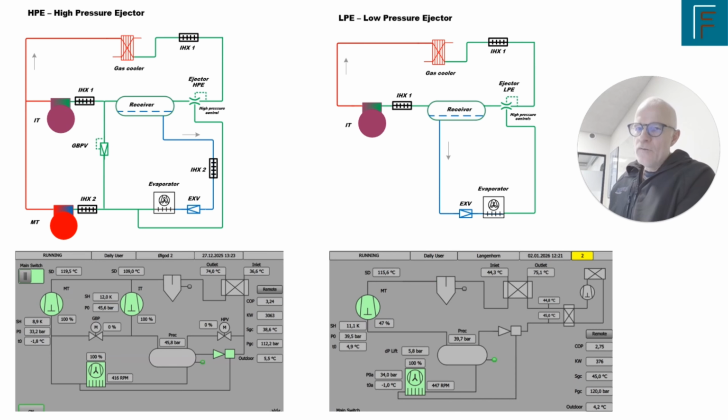It's a little bit more simple with a low lifting ejector, but there are some constraints on when or how we can use it. At FENeject we're only using the low lift ejector on water-to-water heat pumps and on air source heat pumps when the evaporators are very close to the rack or the receiver at the same level. So when the distance is higher and there is a difference in height, then it's not a good idea to use the low lifting ejector system. But the performance gain is more or less the same. It could be between 8-10% using an ejector, so it's really beneficial.